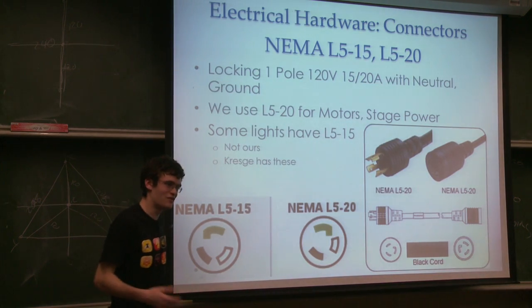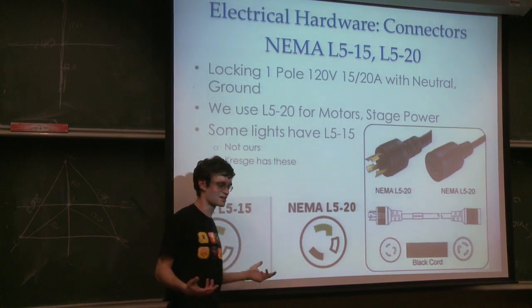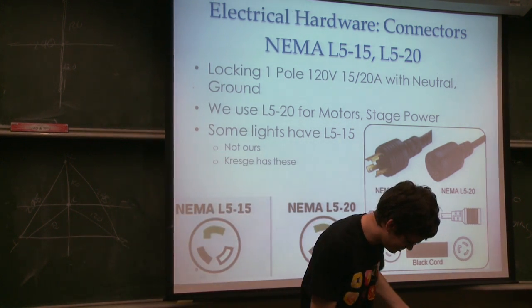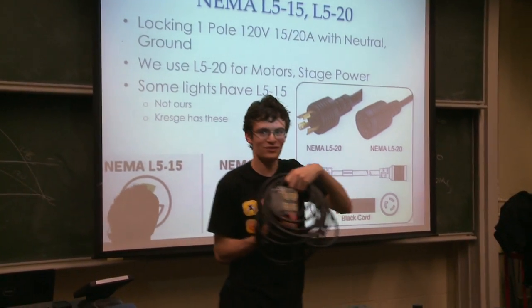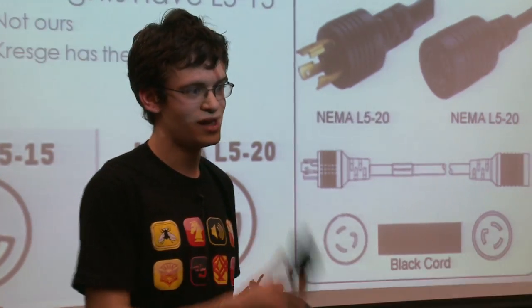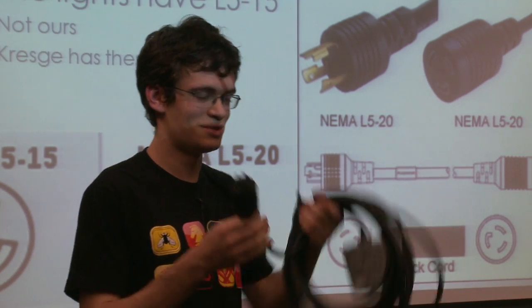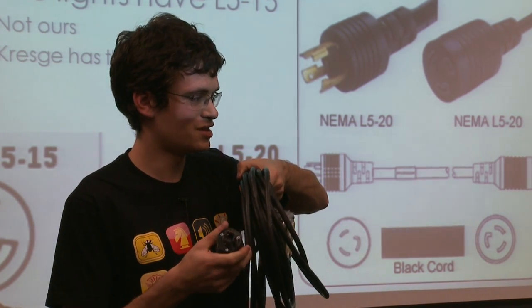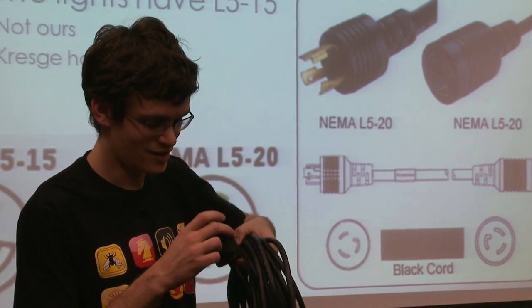So now the L515 520, this is surprisingly enough exactly the same, except it locks when you plug it in. And I have an example of that. This quad box has your Edison 520 receptacles on it, but the plug is L520. And this is because SoundPD has 3 L520 receptacles on it, specifically for this guy. Or does it have 6 520? I thought it only had 3. 6? Okay, 6 520s.